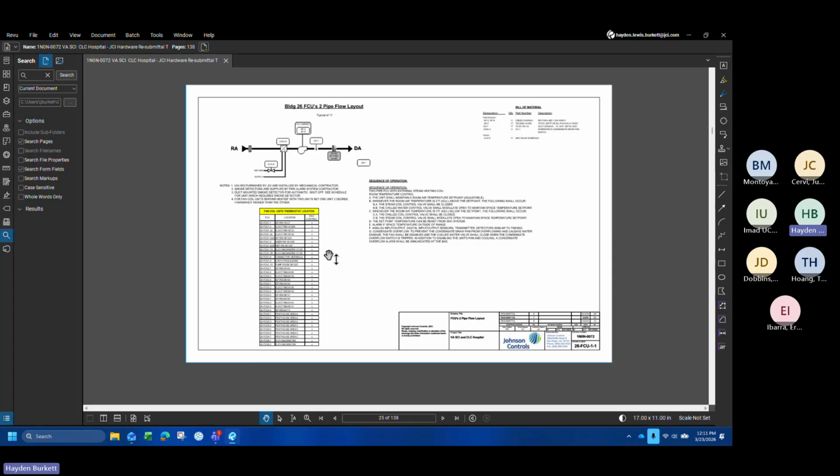So they all ask for different ranges, and they have very specific set points for alarming. So you will know, for instance, when we are too high or when we have too little or too low temperature, right? Okay. So those are actually built in as alarm extensions within Metasys. So you will get some sort of pop-up or notification in Site Management Portal when that occurs, or it will pop up in the event log, essentially.